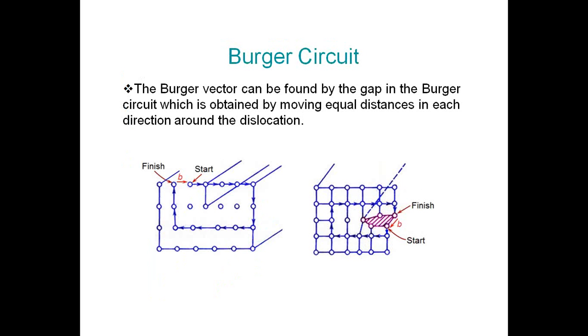So this is the Burgers vector. The Burgers vector we are going to use for the line defect. Mr. Burgers, the crystallographer, devised a method to show the line defect. The Burgers vector indicates the magnitude and direction of the dislocation, or the shift of the lattice line on the slip plane. The method is based on the loop or circle method.